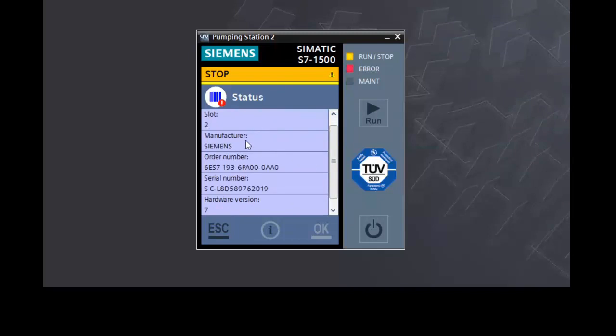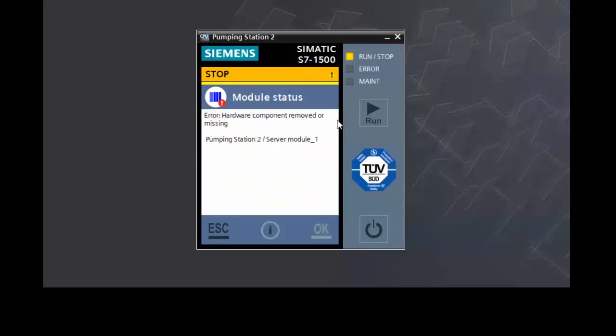Now, if you scroll down, the nice thing here as well is we have the part number on the front screen. So again, if maintenance got called out, found out that the thing had been damaged for some reason, we could start to write down the part number and get on the phone to see who has another one of those available or pull one straight out of stores. You can even see that when it was online, it's pulled the serial number out of that module as well. So we get a nice little error message as well.